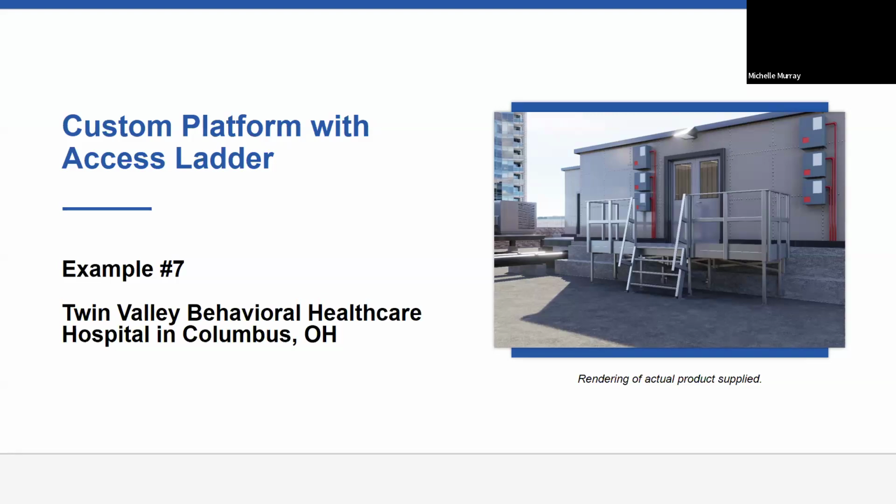The customer provided their requirements to access the units, and because the platforms could not be anchored to the roof, as the warranty for the roof would be negated, a truss system was designed to anchor the platforms to the concrete steps instead. Calcs were submitted and the customer reviewed everything and approved the design. These were shipped pre-assembled for ease of installation, platform and rails assembled. The ladder part was assembled on site and they were all craned to the roof.